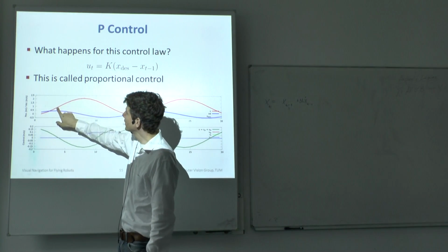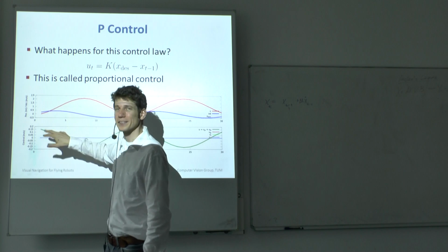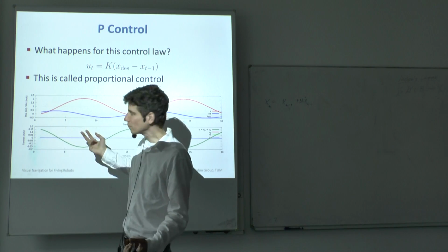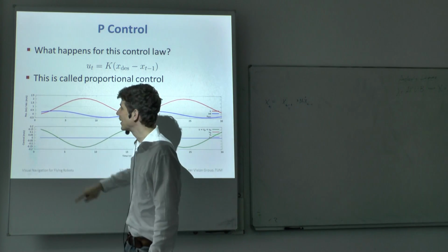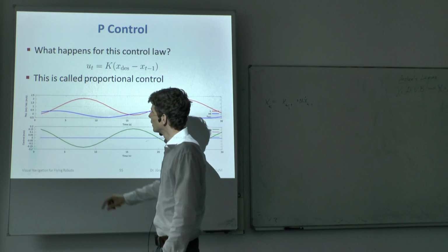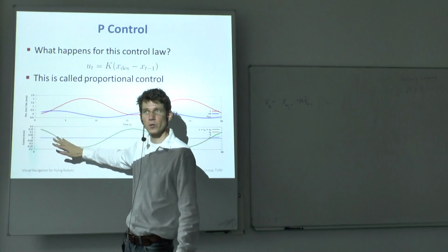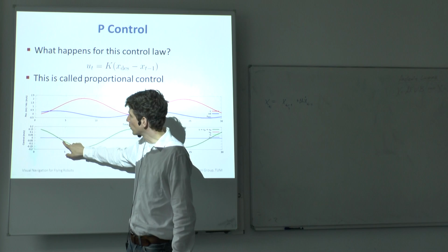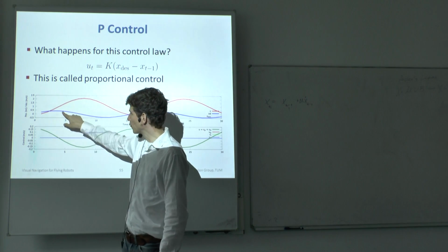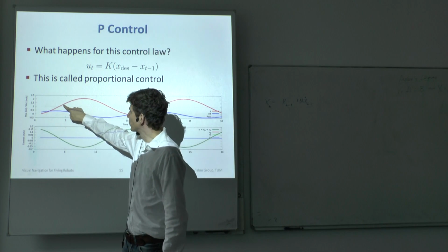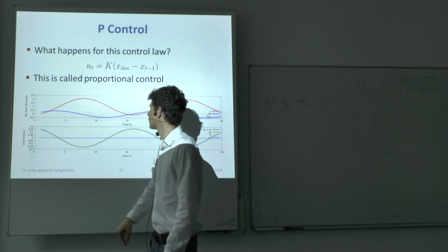But then here at 1, actually we don't stop because our system still has a certain speed. So we actually overshoot our goal, and the system will immediately respond. In this case, we don't have any delays. It will produce a negative force, but because we still have a very high speed, the position will overshoot by a lot, up to 2 here in this example.